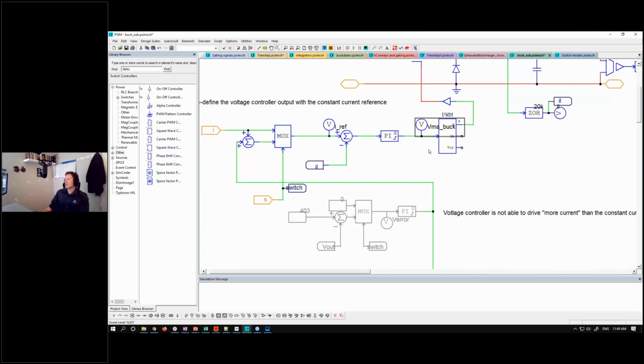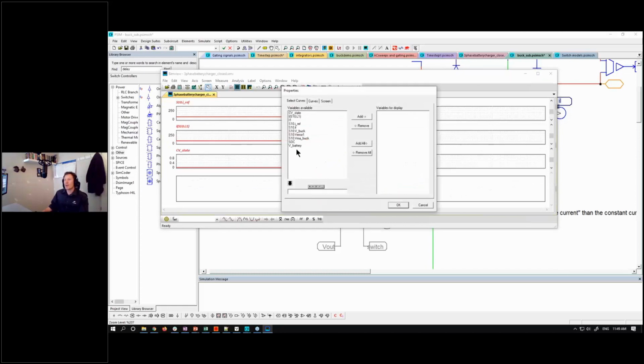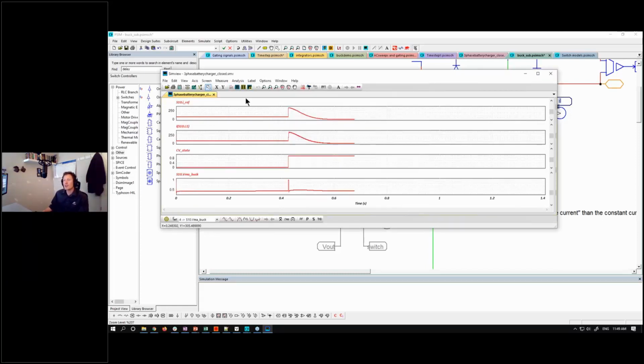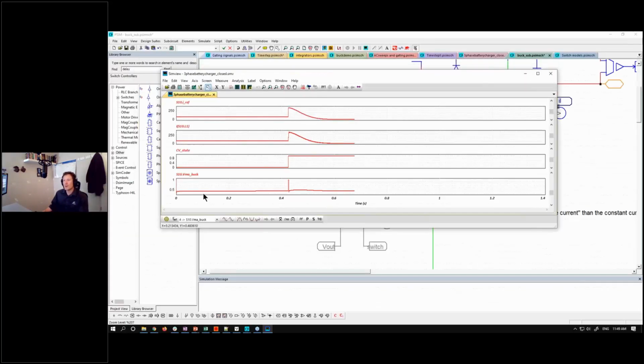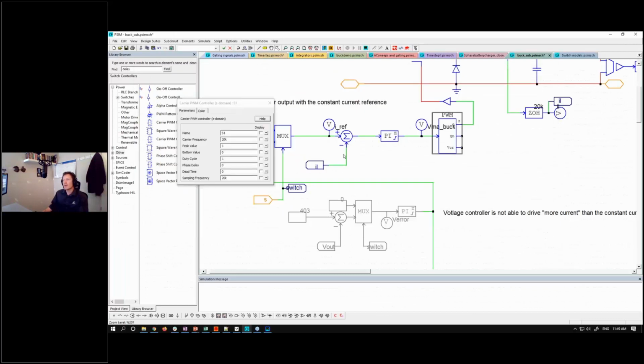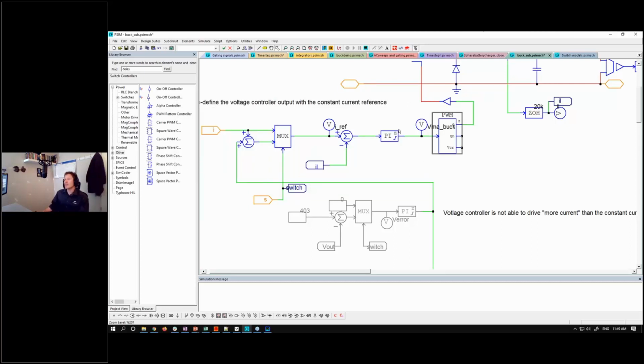If we pull up VMA, the modulation waveform needs to stay within the carrier envelope. So in this case, we're between 0 and 1. The carrier envelope here has been defined as between 0 and 1, so that's okay. Typically what happens is you need to make sure you're inside of that envelope, and that's the first thing to look for.